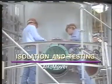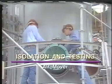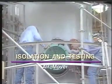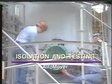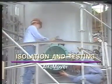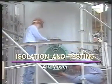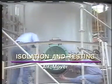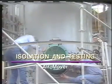After the column is purged and tested for hydrocarbons, one of the manways is opened and an air mover is turned on. The air mover can be a fan or an air eductor like the one shown here. In the event that any hydrocarbon vapors are released during the cleaning of the tower, the air mover will sweep these vapors out of the tower.